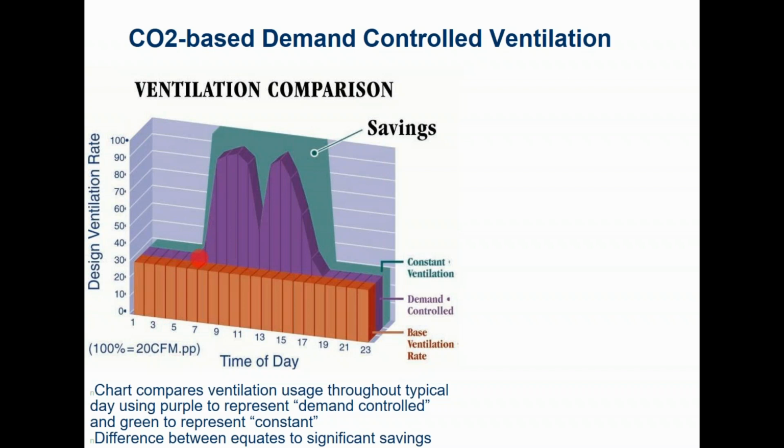So at 8 o'clock in the morning, the building goes occupied. The ventilation damper would go to its occupied position. It would stay there all day long. And then at 6 o'clock at night, when the building closes, it would go back off, right? That'd be a normal system.